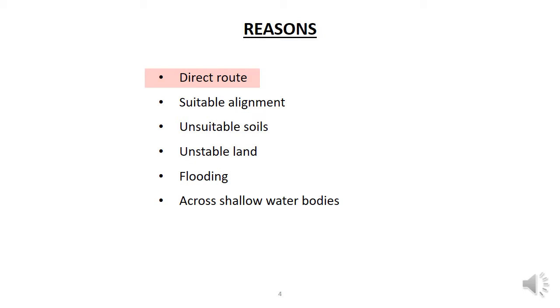Earthworks enable us to provide a more direct route between places by cutting through hills and building above gullies and floodplain areas. They also enable us to build the road to the horizontal and vertical alignments required to provide a smooth, comfortable ride for road vehicles and road users, obviously. Some areas may have soils that are not strong enough to support the road loadings, and so earthworks may be required to improve or replace the soils, or to avoid the problem areas.